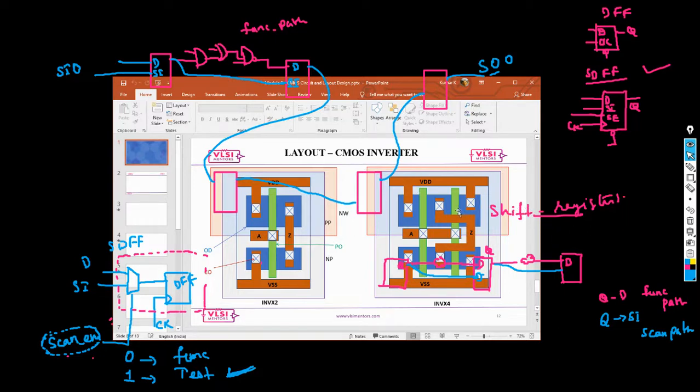Now imagine this is VDD, and this is a signal. If an extra metal piece gets dropped and these two become short, what will happen? There is a Z pin. Say this is your NAND gate, and the internal structure is something like this. Say an extra metal piece or slight variation at the time of manufacturing happens, this might get shorted with your VDD.